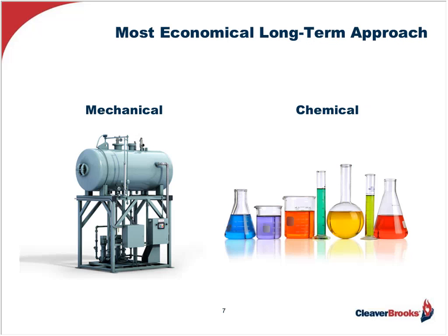So as we stated a few months ago when going into detail about a sound water treatment program, deaeration, though a key factor in attaining a highly efficient and long-lasting boiler system, can't do it alone. We still need chemicals to finish the job, and the amount of the chemicals employed will depend on whether other mechanical devices are in the system, such as water softeners, dealkalizers, maybe an RO, those kinds of things. But suffice to say, at least to some degree, chemicals need to be part of the overall solution.